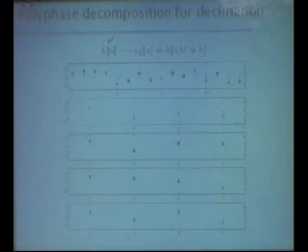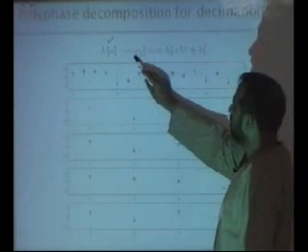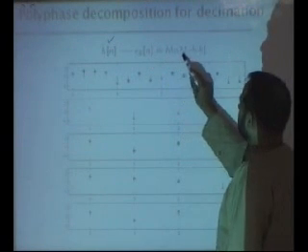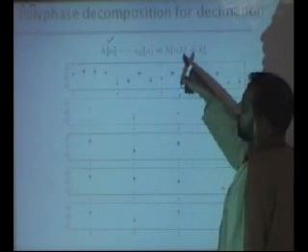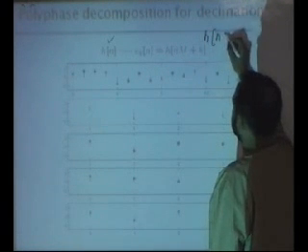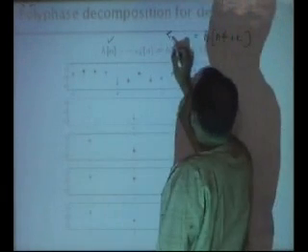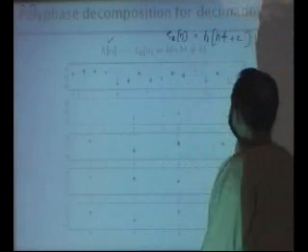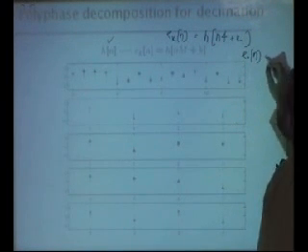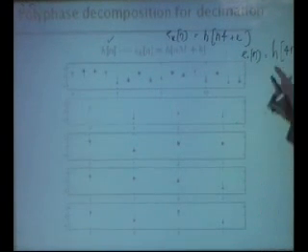Right? This is the first operation I do, and this operation is equivalent to saying that e_k of n is equal to h of Mn plus k, where M is the decimation factor. So let's say M is 4, h of 4n plus k. Let's see what E0 of n is. This is the first filter. E0 of n is h of 4n. So put n equal to 0.